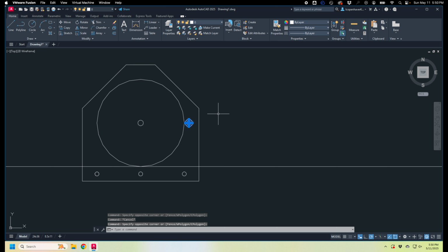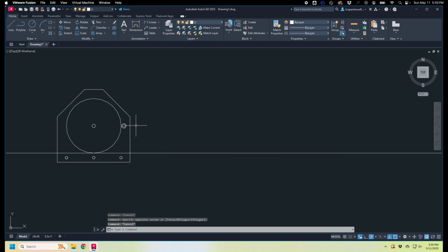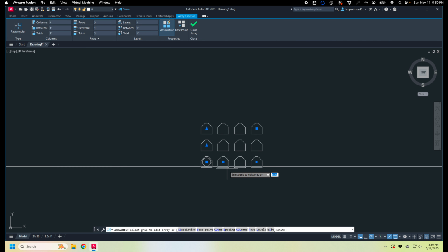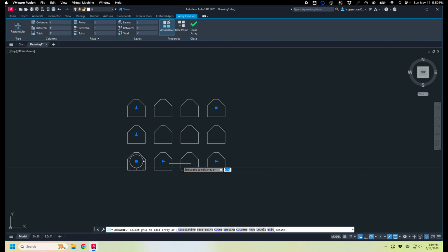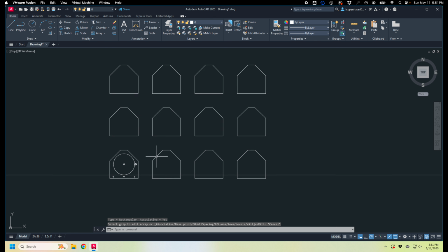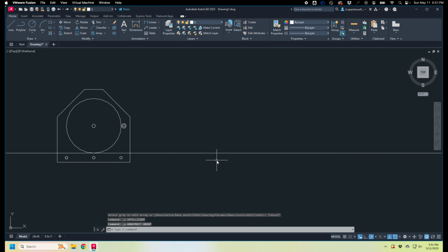is using something called a polar array. So let's talk about arrays really quick. Let's say that I want to do a whole bunch of these. I could array them, and it's just going to give me a duplication of a bunch of them. So it's going to put a bunch of columns and rows, just a series of columns and rows. And then I can adjust those columns and rows relative to that original thing. I can also do, let me Control Z out of that.